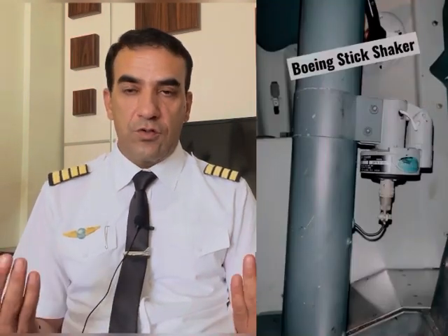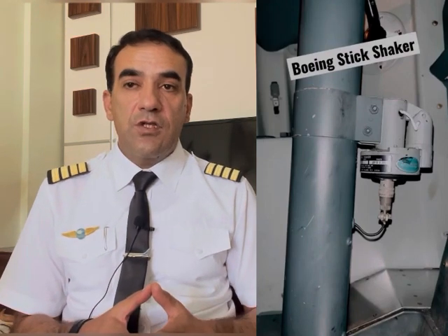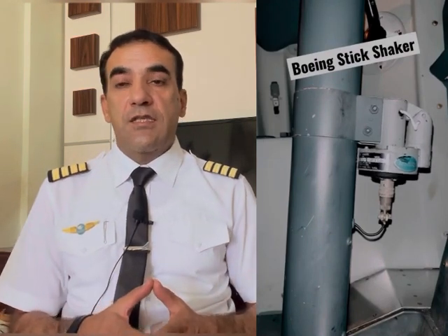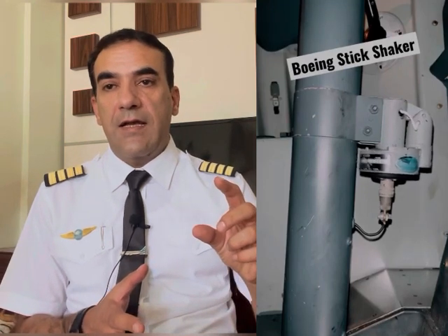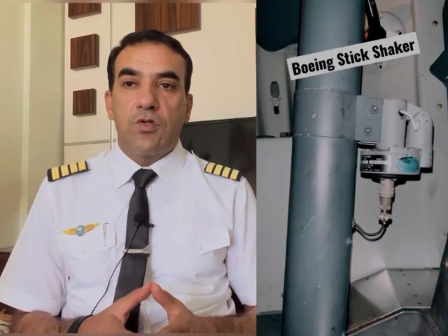Because before the aircraft goes to the actual stall, there is a warning which will be brought to the pilots by shaking the control columns. In this condition, we are not in the stall condition. Still, we have some degrees of angle of attack that we can increase. So this is only a warning for the pilots that, okay, the aircraft will go to stall, please do something, and the only thing we can do is to decrease the angle of attack. But still, if we continue increasing the angle of attack, then the aircraft will go to the actual stall.